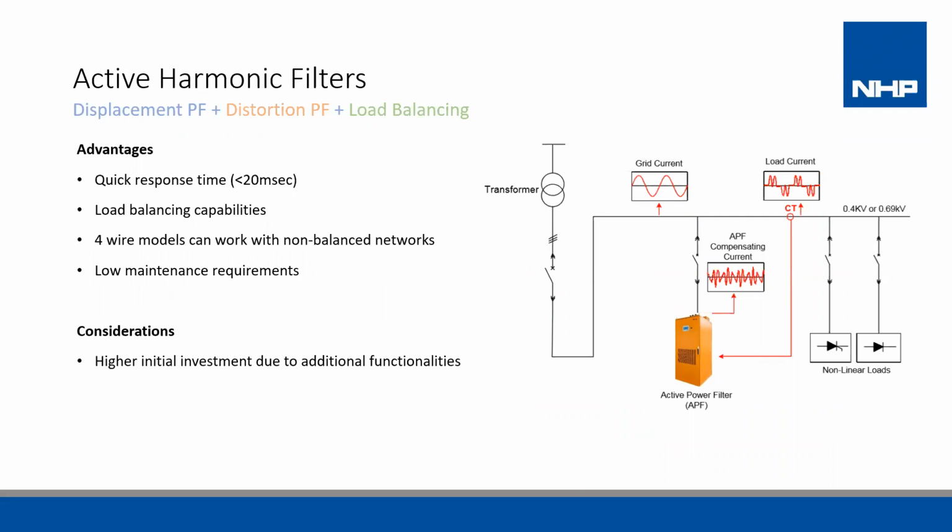The internal structure of the APF is identical to the SVG, but the inverter components or IGBTs do have a higher switching frequency. Some of the advantages are quick response times, as stated earlier, similar to the SVG, 20 milliseconds, load balancing capabilities with 4-wire models, and low maintenance requirements.